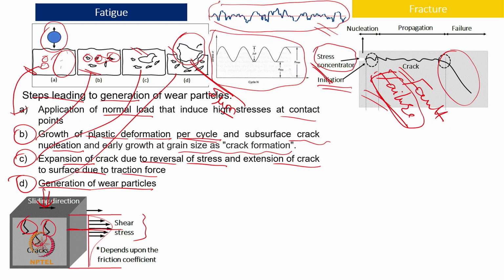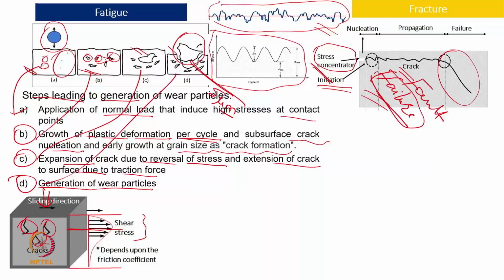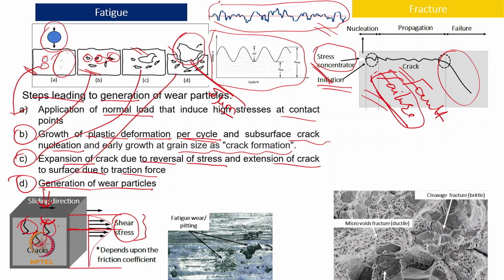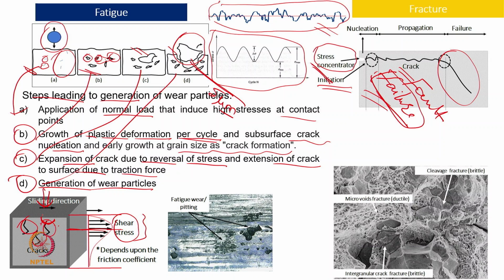It can be related in terms of the Hertzian contact width. There is a possibility, but it happens slightly lesser below the surface. And there is a normal stress, and because of that maximum principal stress will happen somewhere, which causes the crack to propagate and come finally to the surface. So there are theories which will justify these kinds of reasons.